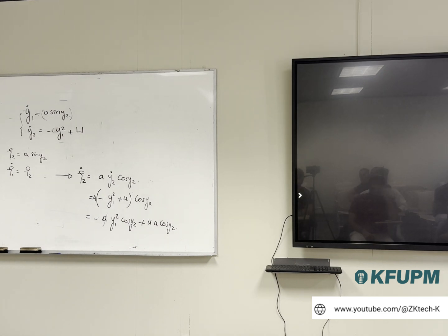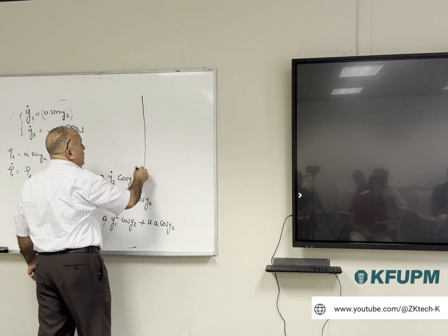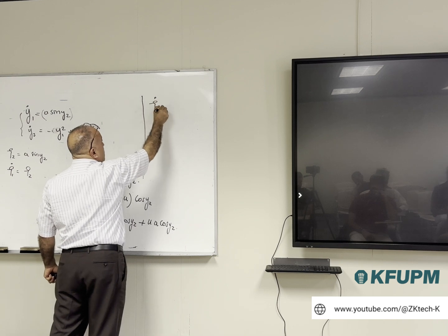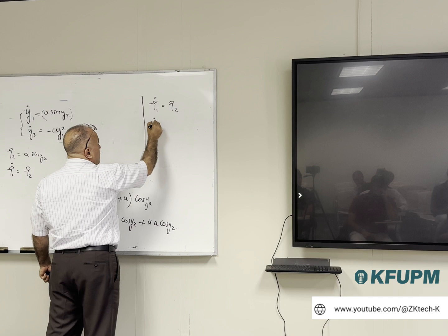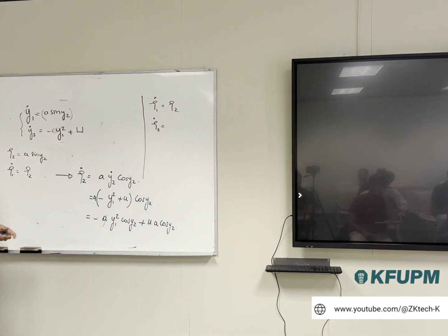So using this transformation, I was able to move from a system where we have two nonlinearities, one at the level of the state, one at the same level of the controller, to a system that is linear. Now we have, not linear, sorry, linear in one state, so zeta 1 prime is equal to zeta 2, and zeta 2 prime is equal to, I need to write everything as a function of zeta 1, zeta 2.